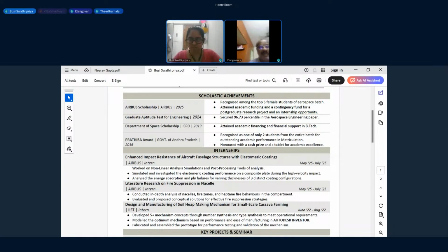Your aerospace structure means all the fundamentals have to be known. You know what is Bernoulli's equation in aerodynamics? Yes, sir. What is that? Pressure P by rho plus V square by 2 plus GZ is equal to constant, which means the mechanical energy across the streamline is constant.